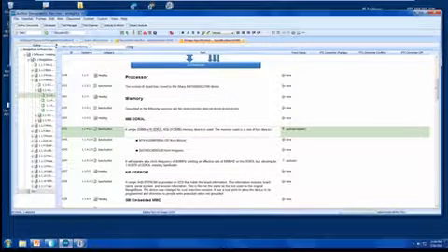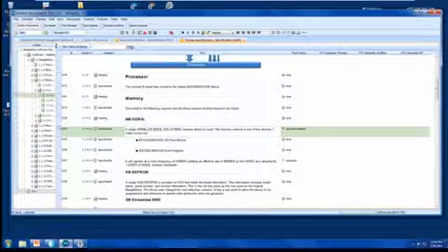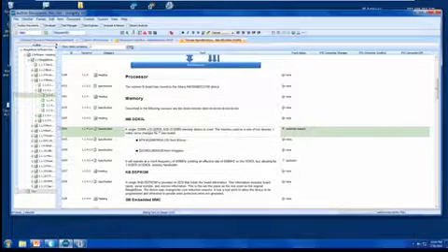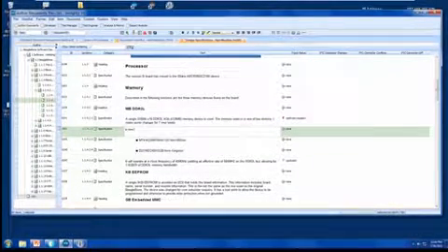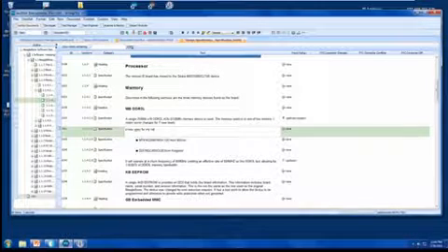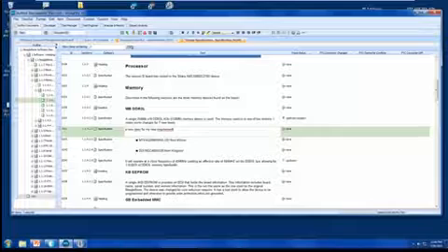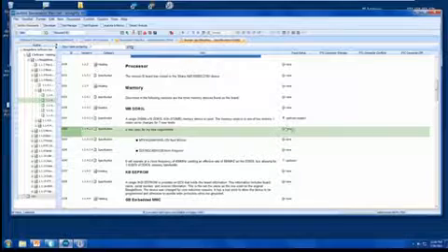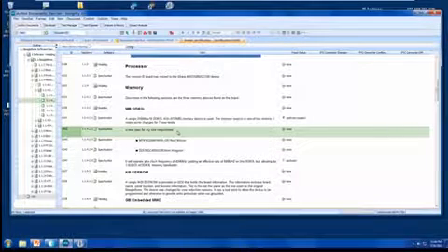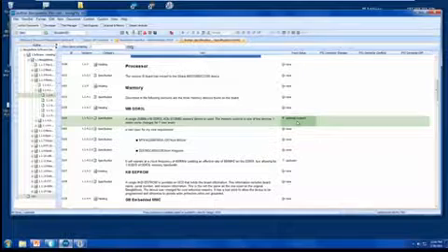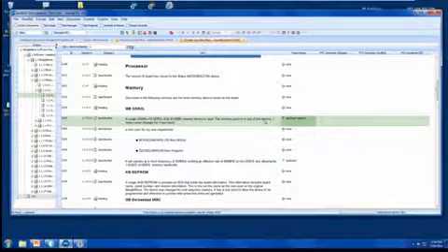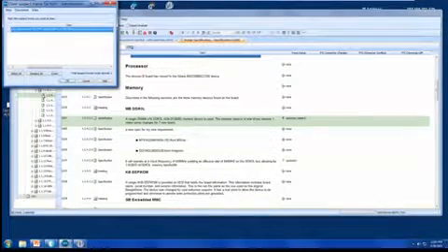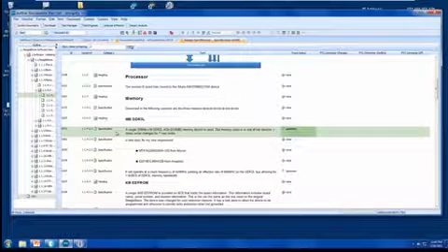Pardon me. And let's say I make some changes for 7 new levels. And I'll say a new spec for my new requirement. In addition to that, what I'll probably want to do is create a traceability link from this spec back to that requirement. Oh, and before I do that, I think that this is okay. The changes shouldn't be too bad, so I'm going to clear that suspect link. This is the one. Clear it. And we see that we've got the cleared suspect link here.